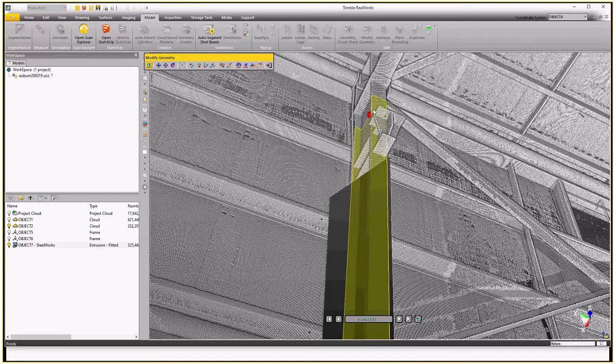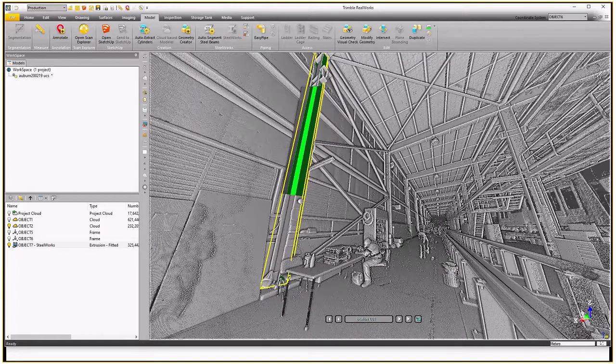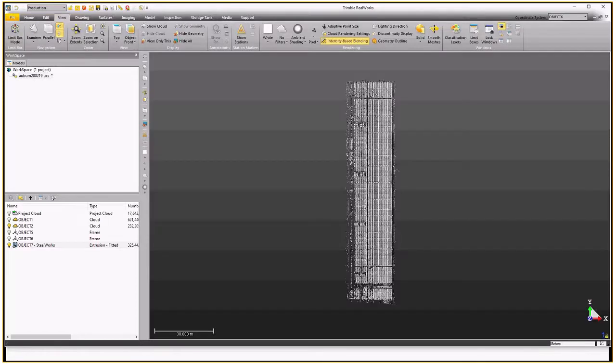Now for all these other beams, I had a bit of a cheat before we got on. I measured between these beams and they're basically 8 metres. I've also set this job up on a UCS, a user defined coordinate system, so the y-axis is running along the beams. On a lot of these jobs, it's a smart thing to do because it allows us to duplicate and shift data along the axes, which is a nice, quick, easy way of doing it.